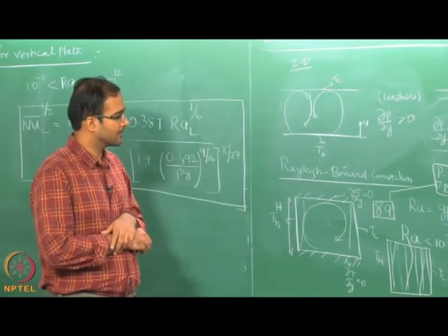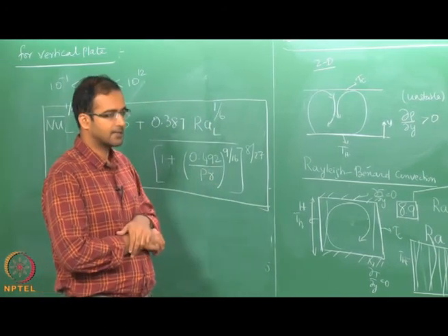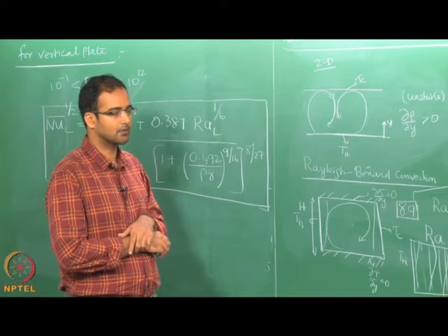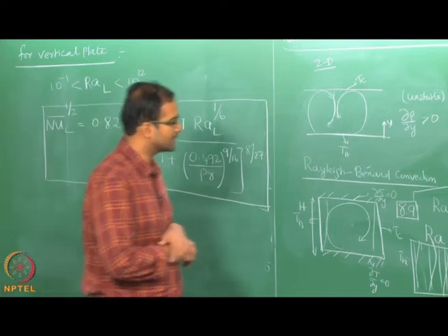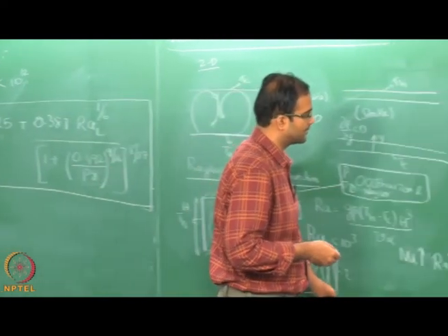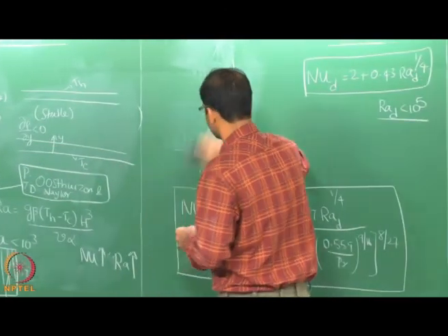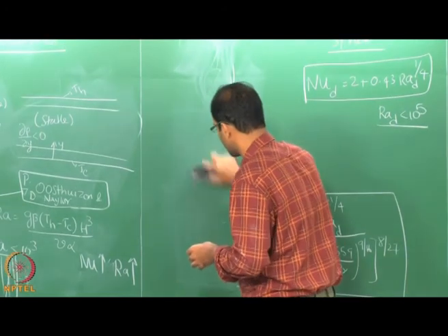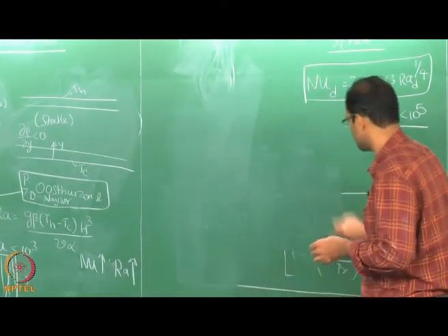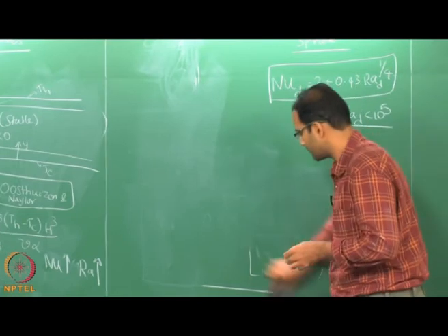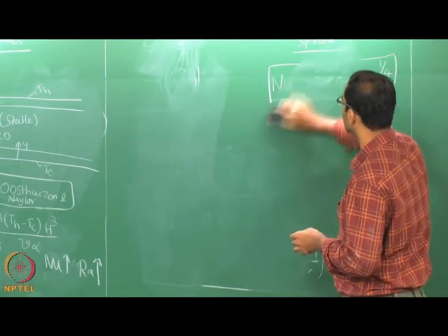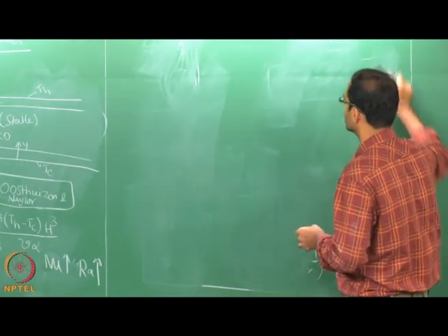Especially look at this section. He has very nicely shown that the way he is solving these equations is by what is called the stream function vorticity method. Rather than directly solving the continuity and the momentum equations, because if you use the stream function, it makes the continuity equation redundant.